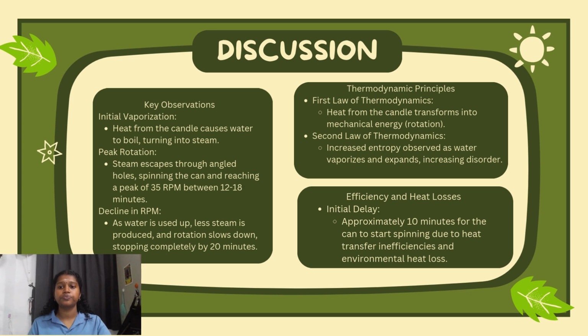by 20 minutes. Here are some key thermodynamic principles observed in the soda can steam engine experiment, along with the potential sources of inefficiencies and losses. Energy transformation: the chemical energy from burning the candle is converted to thermal energy in the form of heat. The energy increases the internal energy of water, causing a phase change to steam. The high pressure steam is expelled, converting thermal energy to kinetic energy. This demonstrates the first law of thermodynamics, energy transformation without creation or destruction.